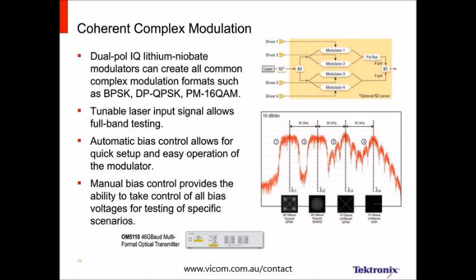Down here is an example of the spectra that you can get out of a lithium niobate modulator. And a lot of this also applies if it's indium phosphide. On the far right is what you get if you do basically on-off, fast rise time switching. You get these multiple-lobe sinc functions that happen because of the fast rise time. It's basically the Fourier transform of a square pulse. And so the spectrum ends up being a lot wider than you might expect. This is for a 10 gigabaud signal.